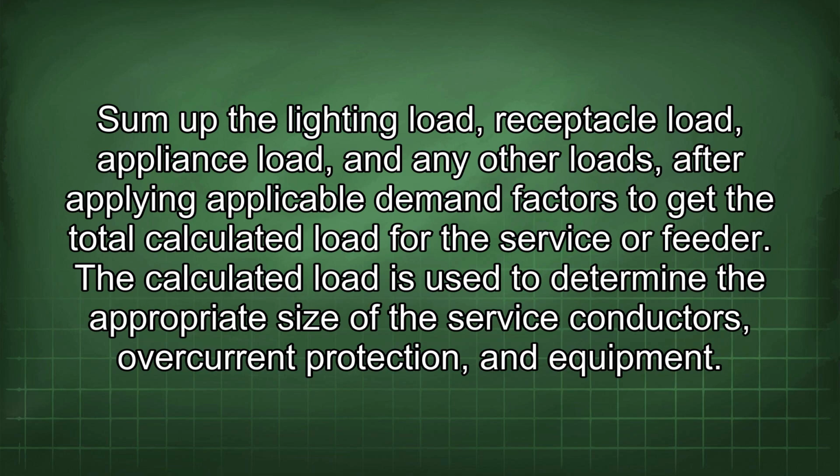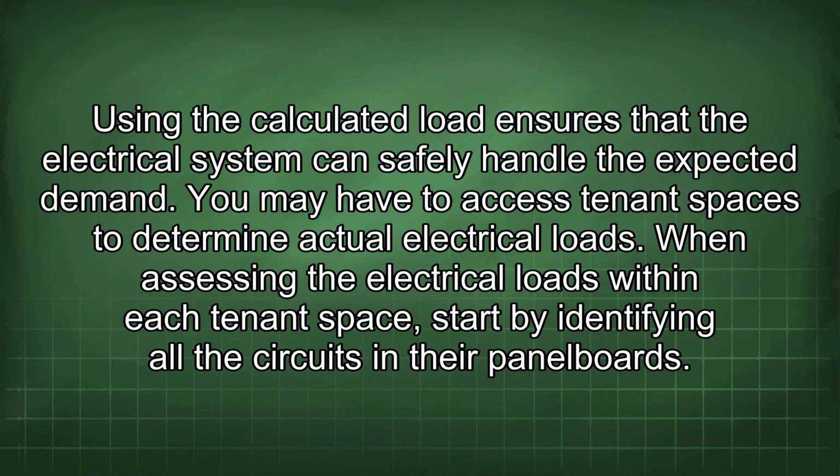The calculated load is used to determine the appropriate size of the service conductors, overcurrent protection, and equipment. Using the calculated load ensures that the electrical system can safely handle the expected demand. You may have to access tenant spaces to determine actual electrical loads.